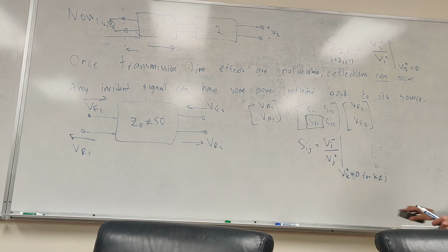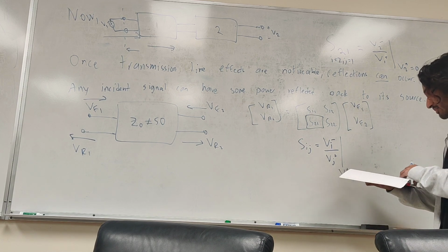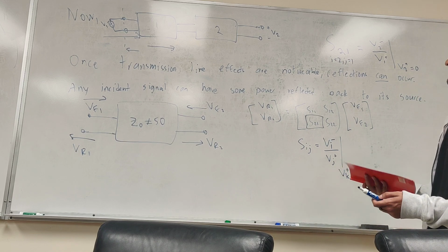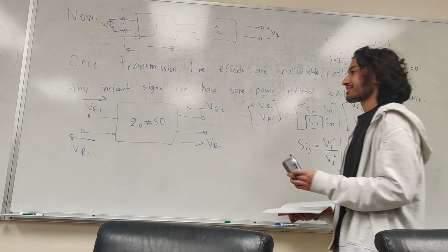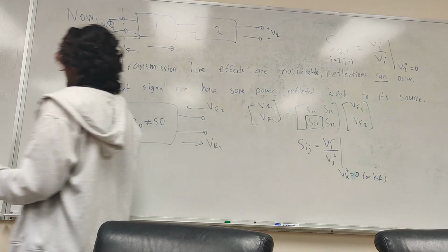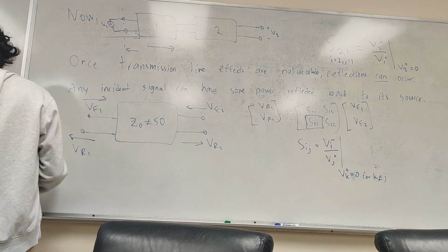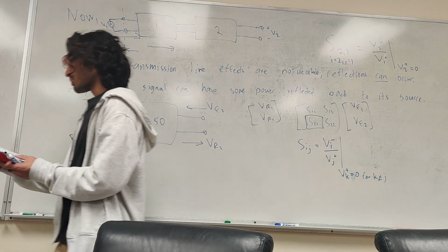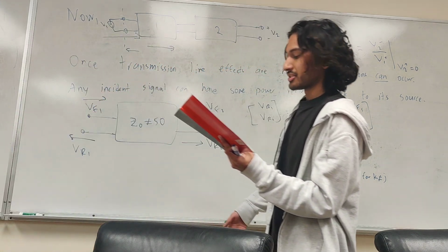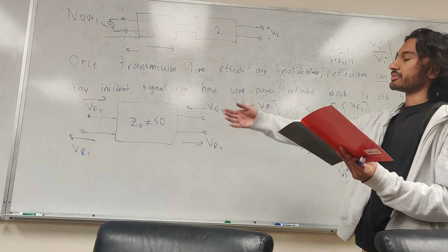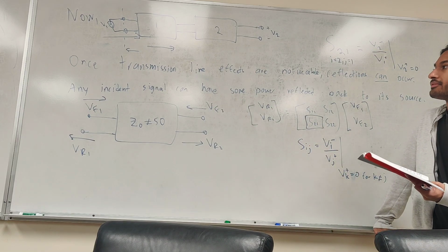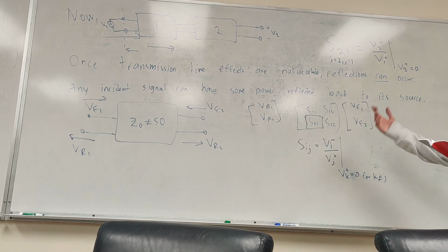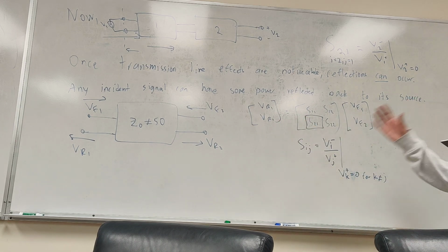Go. So, next step, and this is where it gets a little tricky. This part, you don't have to understand in the slightest. It's a more nuanced detail about things. But at 27 megahertz, we use S parameters to determine the gain of our filters, right? I did the filter before. But I already said, hey, at 27 megahertz, we don't have the phase delays, which means we don't have a transmission line effect, which means nothing is physically reflected. But we still use S parameters.